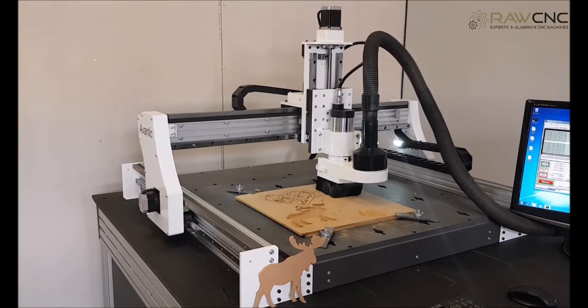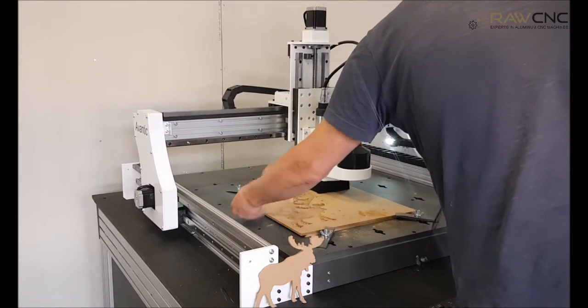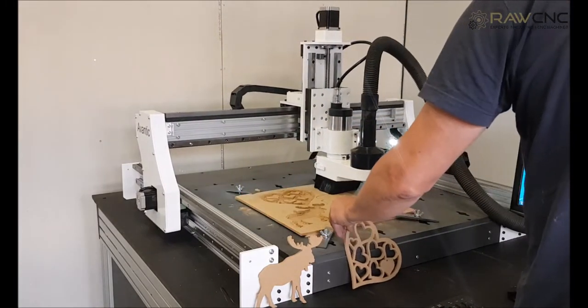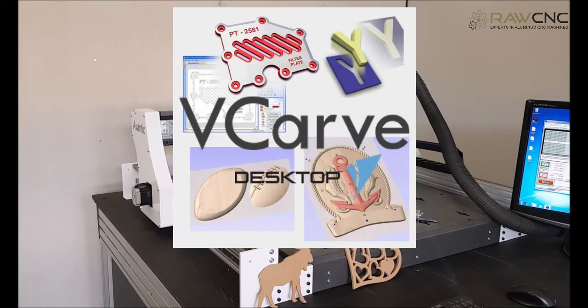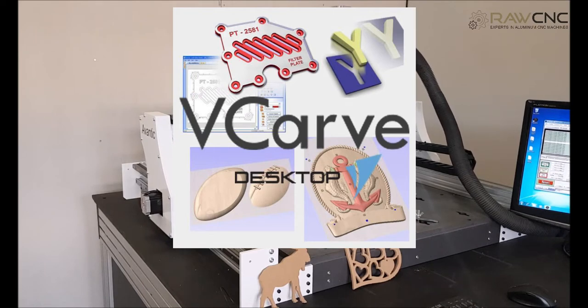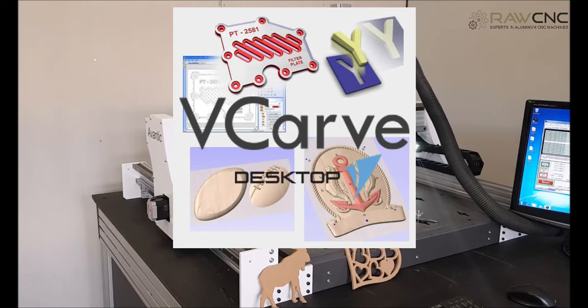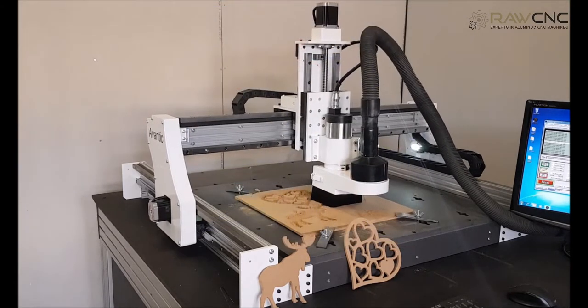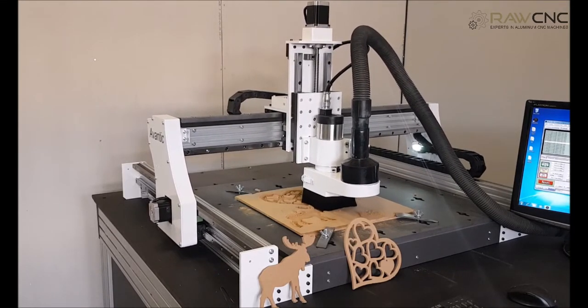There are a variety of drawing software, both free and paid versions. Search for vector drawing software. The second program we need is a CAM software. With a CAM software, we will tell the CNC machine how to cut the file. There are various CAM softwares on the market, both free and paid versions. We recommend and include Vectric's CAM software with our machines. But before we look at the CAM software, we are going to go through different ways to cut with a CNC machine.